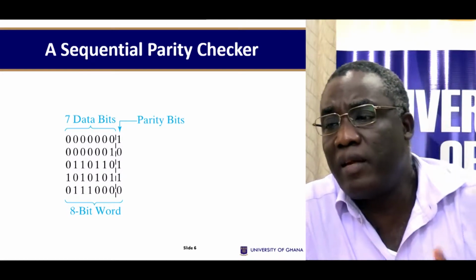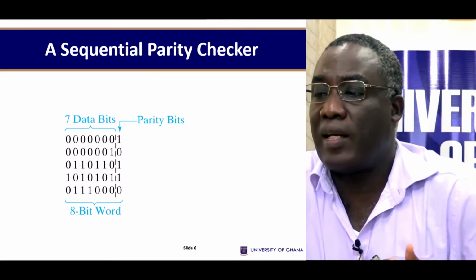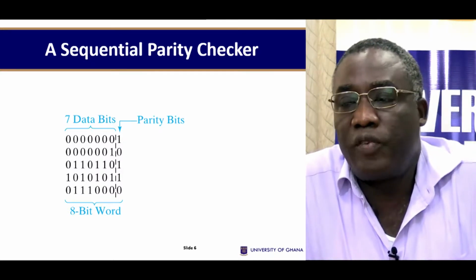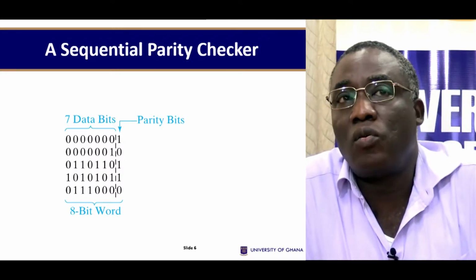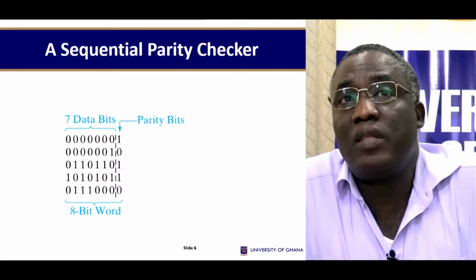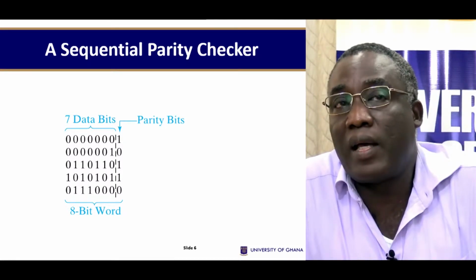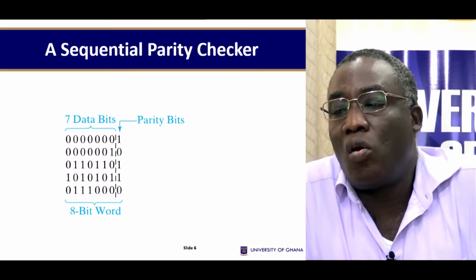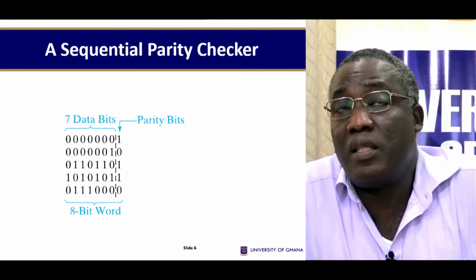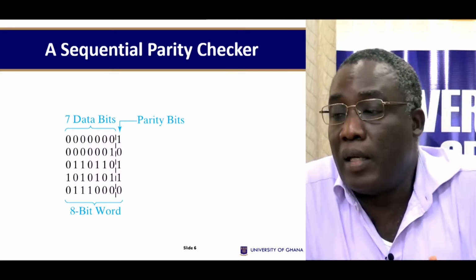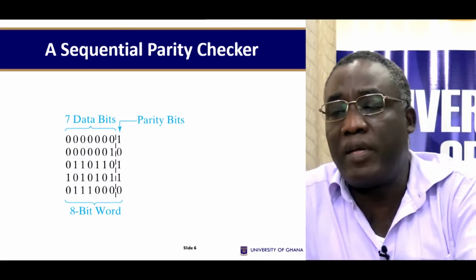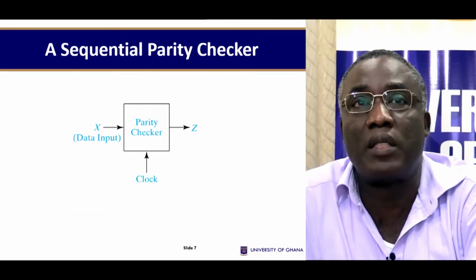When binary data is transmitted or stored, an extra bit is normally added for error detection purposes. For example, if data is transmitted in groups of 7 bits, an 8th bit will be included as a parity bit. Alternatively, the parity bit could be used such that the total number of ones in the blocks is even or odd. So you can have odd parity or even parity.